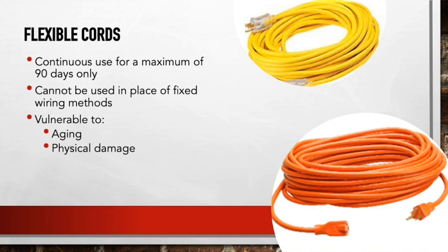So essentially, a maximum of 90 days can they be used, so they can't be used to have things plugged in permanently. They cannot be used in place of fixed wiring, and are vulnerable to aging and physical damage. That's kind of the reason. Nicks, cuts, they get brittle, old, they change color. Most of us have seen this.